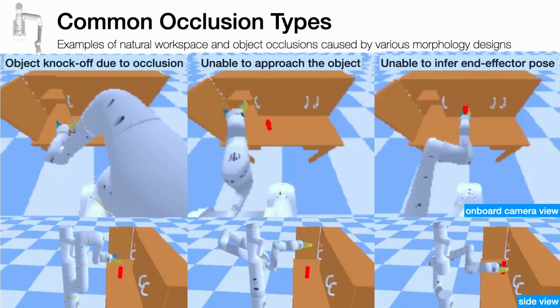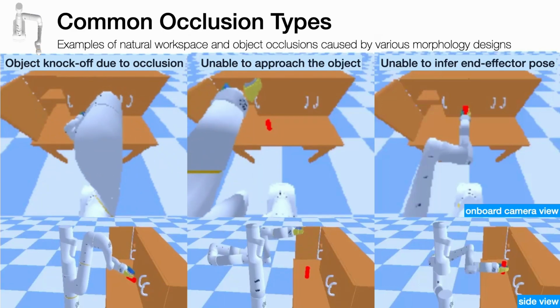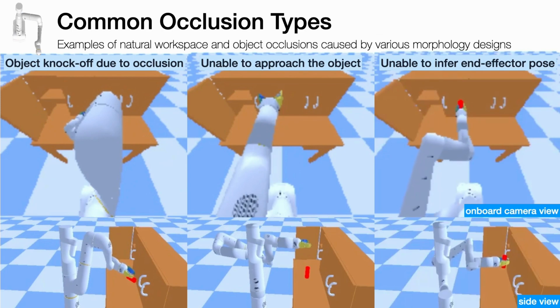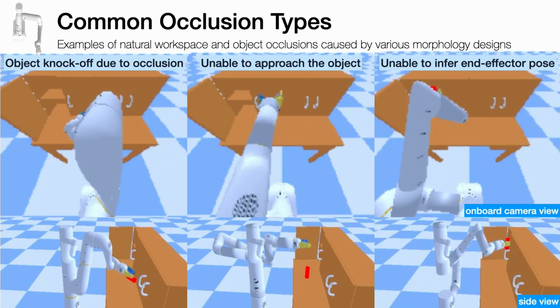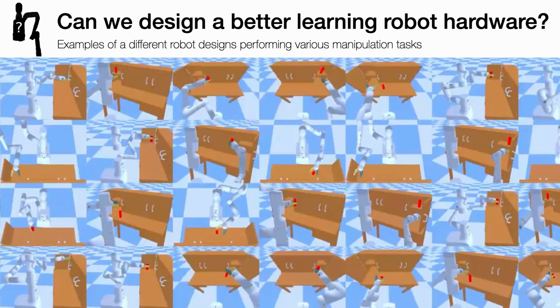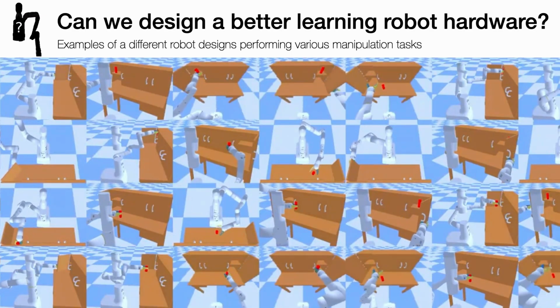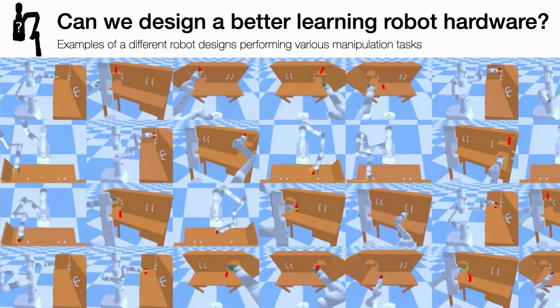However, the current robot design practices overlook the impact of perception and design choices on robots' learning capabilities. For example, robot morphology can interfere with the robot's visual sensor and prevent it from observing critical task-specific information, leading to degraded robot learning and performance. Such scenarios motivate us to explore hardware optimization without neglecting the interplay between the robot's design, onboard perception, and their interaction in different tasks.